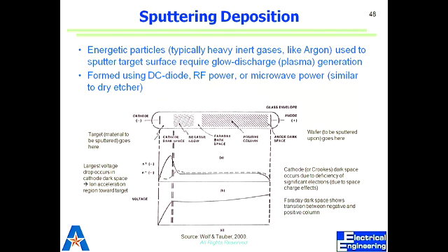So now this plot tells us, from cathode to anode, we have different quantities of ions and how voltage changes within the substrate. There is a region called dark space, and then we have negative glow, then ultimately we have our wafer on this side which gets the sputtered material to deposit there. Right? Question?